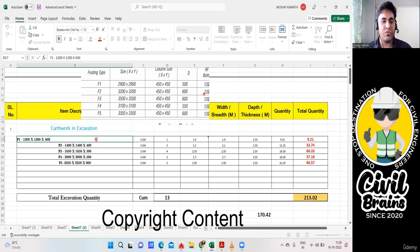Now F1, quickly write the footing name. 2900 by 2900, and what is the depth of your footing? It is 500. So F1 is done. Similarly, write for F2. F2 is 3200 by 3200 and by your depth. See, this D you can see is the depth, I'm taking 600. Similarly, go for F3. F3 footing is 3500 by 3500 by 600.